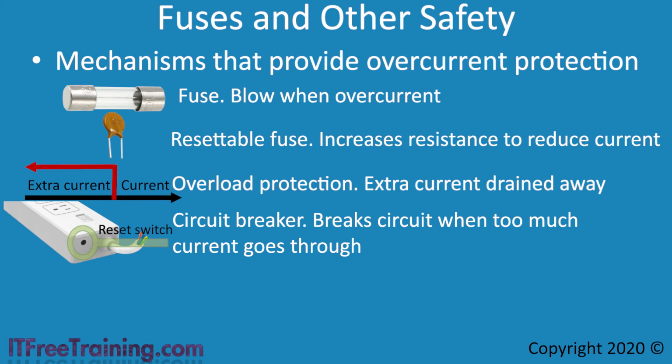Doing this increases the amount of current that will be going through a single wall socket. This is also the same reason you should not put multiple high current devices on the same power strip, such as, for example, multiple air conditioners.